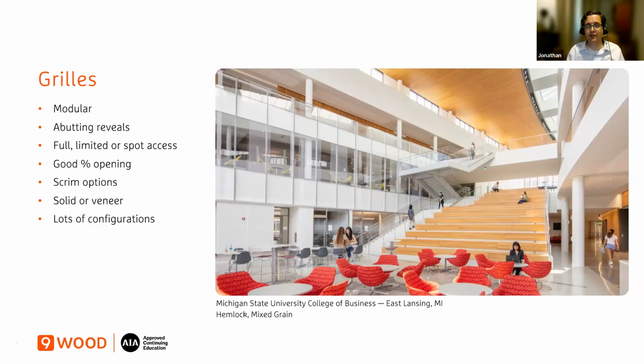And the other thing is wood is, the technical term is hygroscopic. And so it continues to move, even in interior environments that have HVAC, as the relative humidity changes. The wood will shrink and expand. And sometimes it can be significant depending on the situation, even in a normal building. And so over time, that half-inch reveal helps prevent that kind of variation from standing out, versus if you had a really small 1/8-inch reveal, even a 1/32-inch deviation might read if you're looking down a long reveal line, and you want to avoid that. So you need the right reveal to help deal with the normal accumulated tolerances and wood movement.